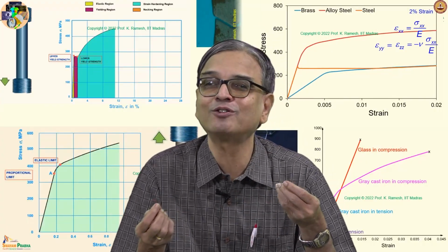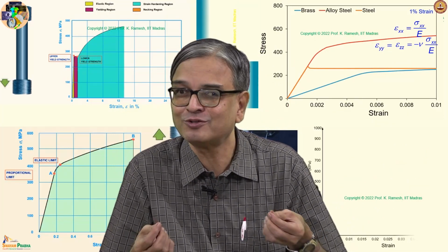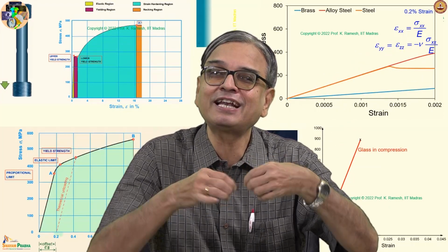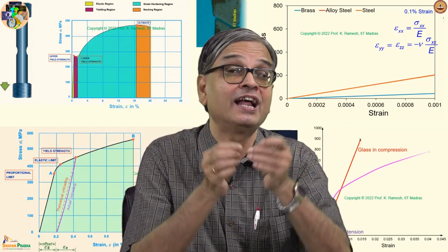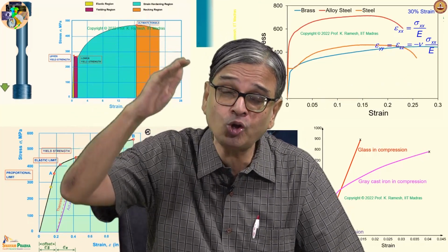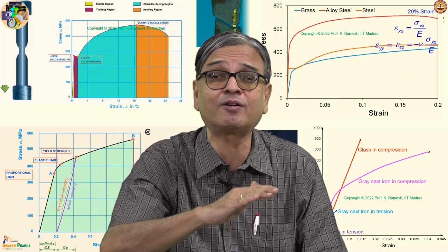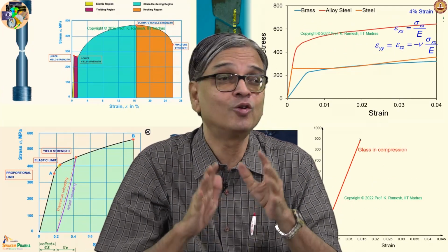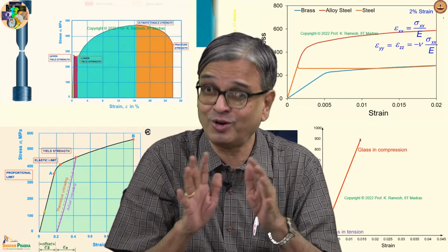Is the idea clear? And scientists want to relate it to this: suppose we are on the 3rd floor, and I ask you to go down and come up once, you will not mind. I ask you to do it 10 times. At the end of 10 times, what will you say? I am fatigued. Will you say that or not? Same thing they have coined it for the material. So, when I apply repeated loading, it fails by fatigue, and I will operate at much lower load than what we have discussed till now about monotonic loading. So, we are justified in looking at a linear elastic theory.